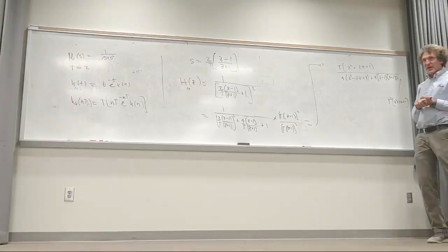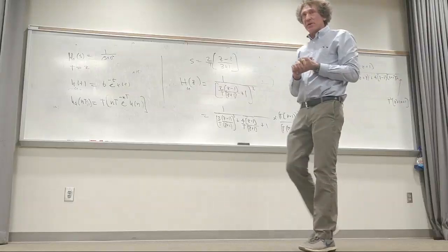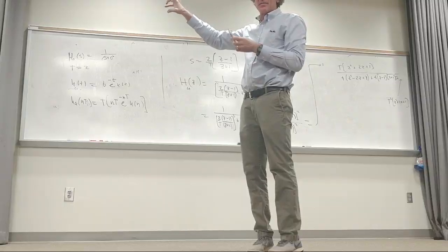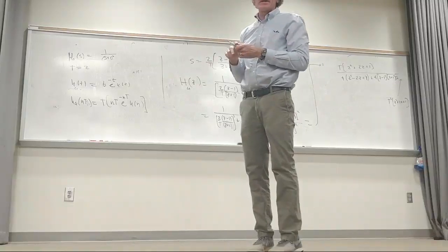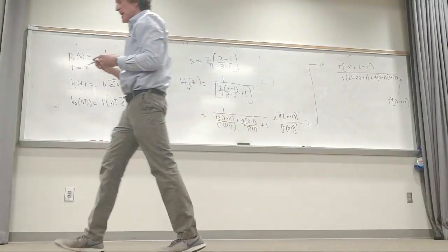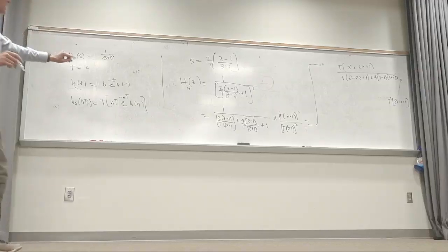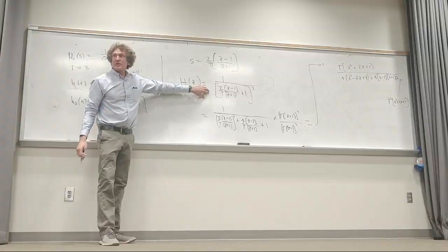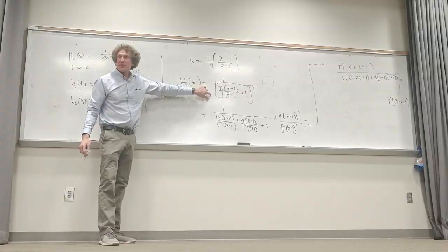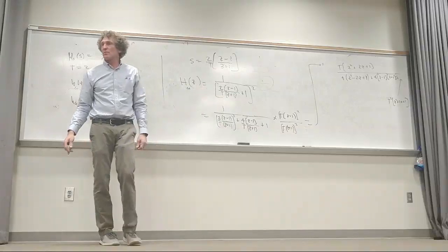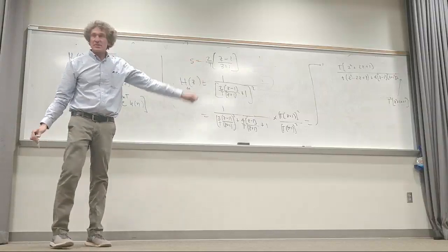And then if you have that, if you wanted h of n, you can go ahead and take 1 over 2 pi, the integral from minus pi to pi of that H of omega times e to the j omega n d omega, if it's a feasible integral. Or what you can do right here is do an inverse z transform of that. This is maybe easier. Did he do an inverse z in this book to get that? That'd be easier probably, but either one will work. And you can get the filter properties by doing what I showed you there.